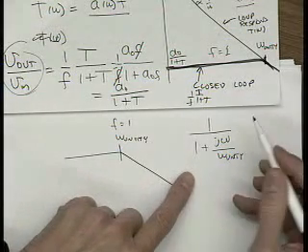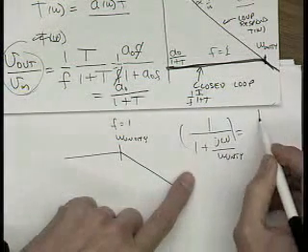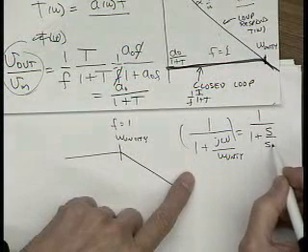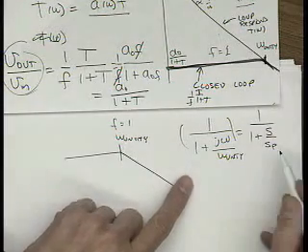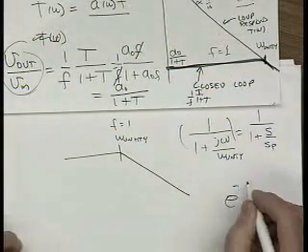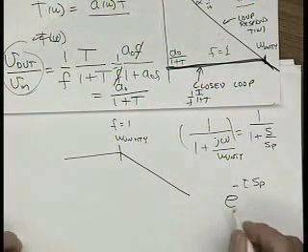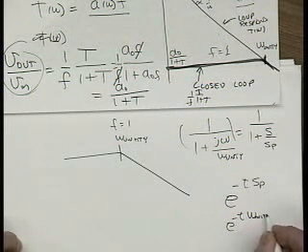If we go to the Laplace domain, this is like 1 over 1 plus s over sp. The response of this thing will be equal to e to the minus t times sp, or roughly e to the minus t times omega unity.